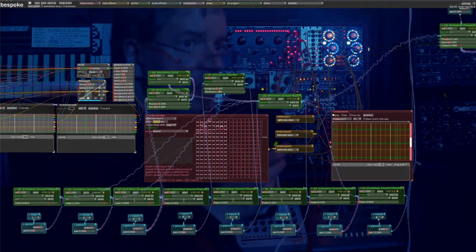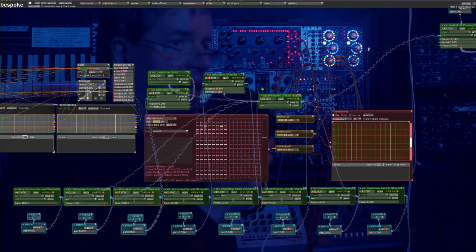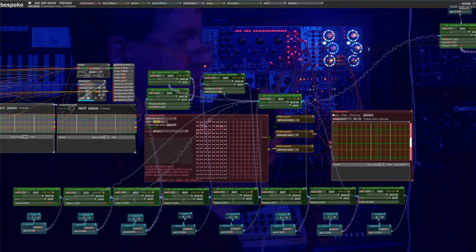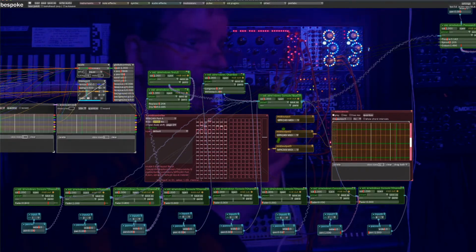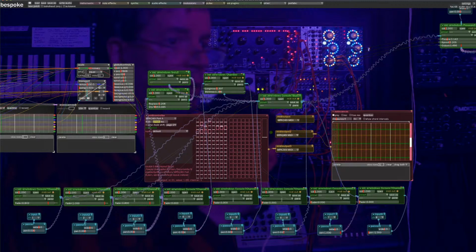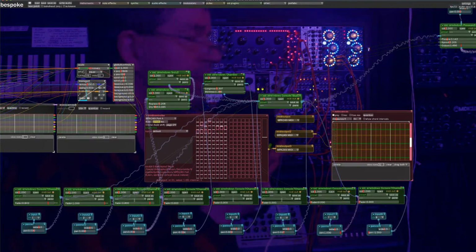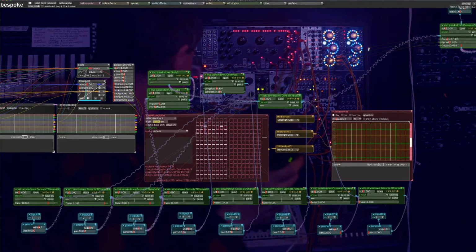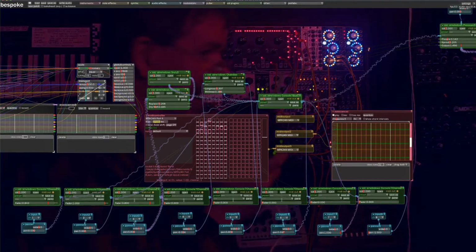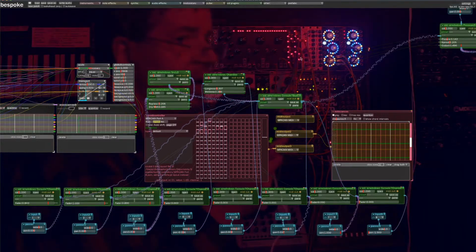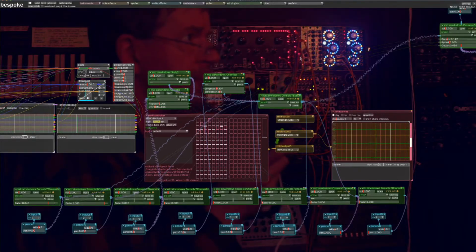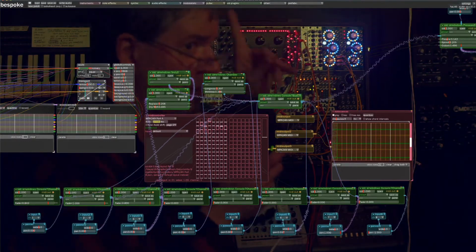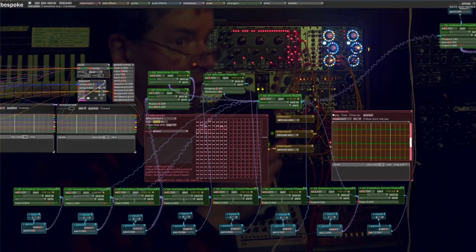And I could probably do with a bit of an attenuator here to kind of dial it back, because I have a Sloth here which is able to give me very slow evolving changes, but I'm not necessarily going to want to put big voltage changes into here. The changes it's going to want are very minor. So I need to be able to turn it down, and patch cords with a lot of resistance would also do that, like attenuator patch cords would. I don't have those at the moment, but I could make them fairly easily.